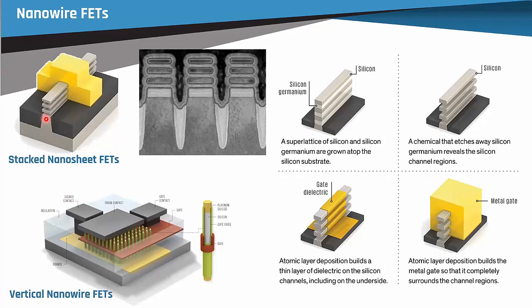And what seems to be the winner of the next type of transistor that's coming out there, which I can explain afterwards how it's made, because this is pretty crazy, are these nanosheet FETs. Intel, of course, doesn't call them nanosheets, they call them nanoribbons, but they are these type of wide nanowires.